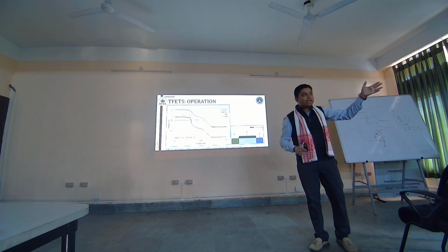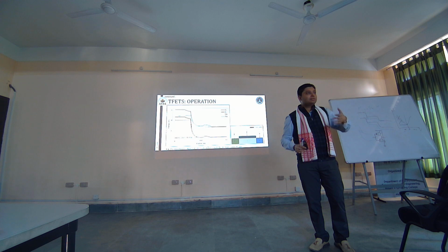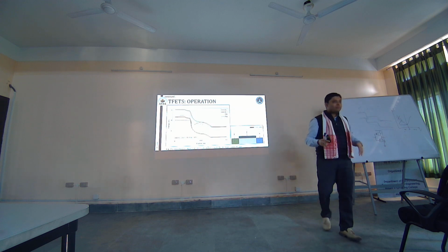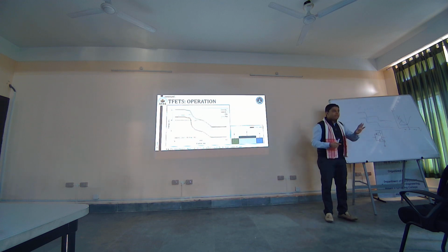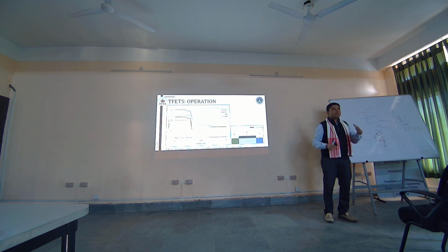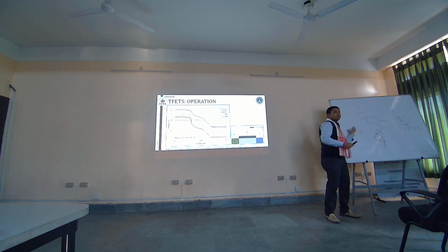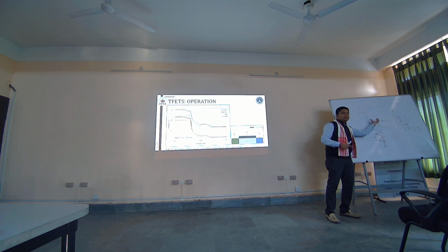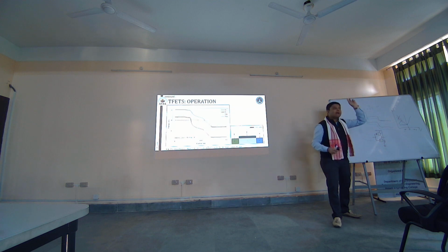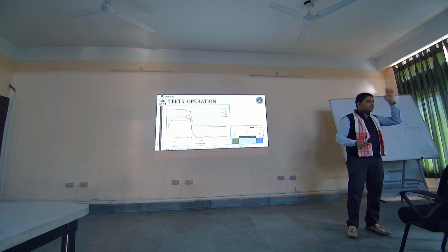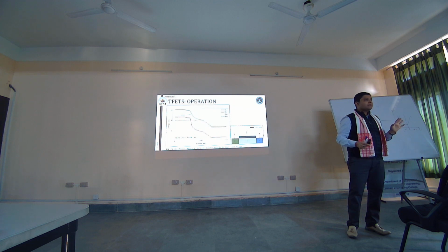If there had been no gate, then things would have been easier, although the current would have been very less. So what we are getting as conclusions as of now is that I want conduction in this part, but I don't want conduction in this part. I want conduction on the positive side, I don't want conduction on the negative side. But again I have only one gate which covers both the junctions. Are you getting my point? Where is the problem? So what can we do?